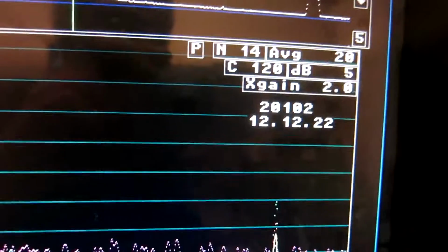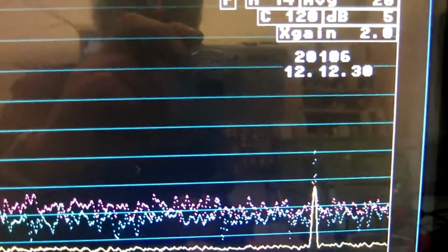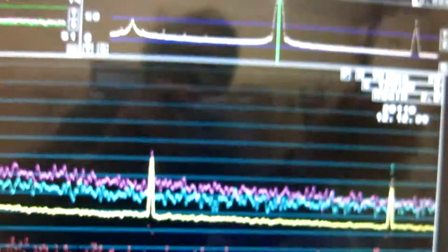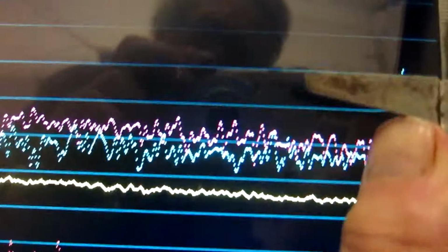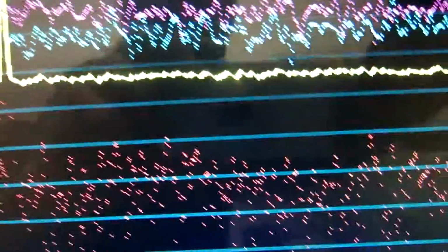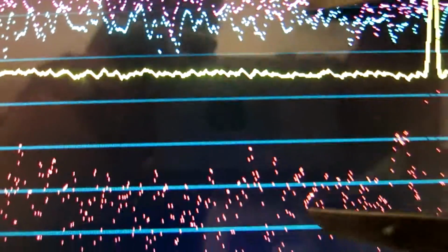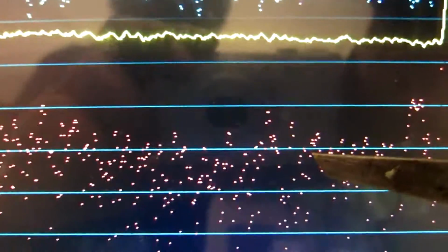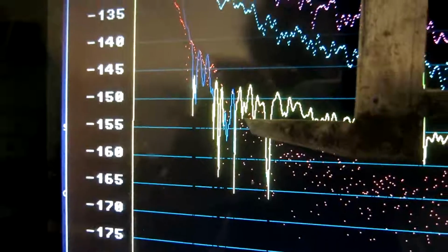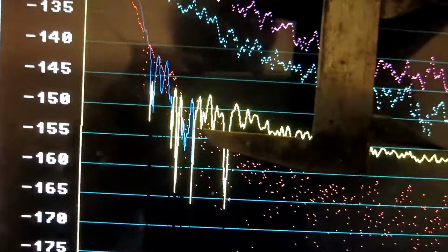With 20,000 averages, the correlation advantage is the square root of 20,000. That's 21.5 dB. So going from the raw data to the detected FM modulation, I find the imaginary part at this 21.5 dB down. And then I can follow it, as you can see here, but at this point, and that is above 10 Hertz, the correlation advantage isn't big enough.